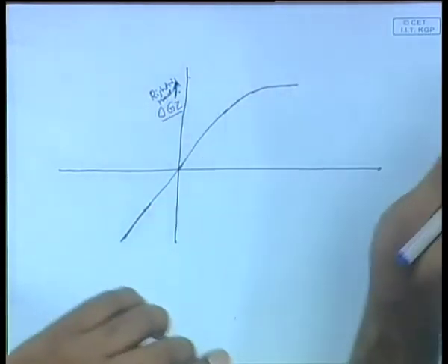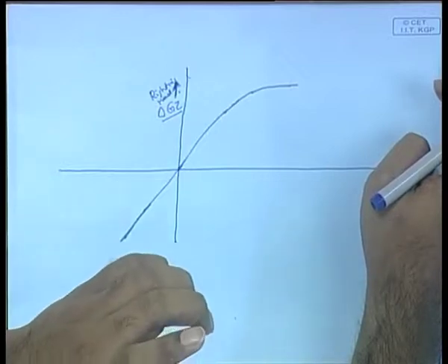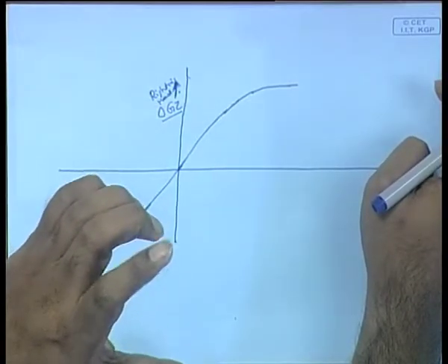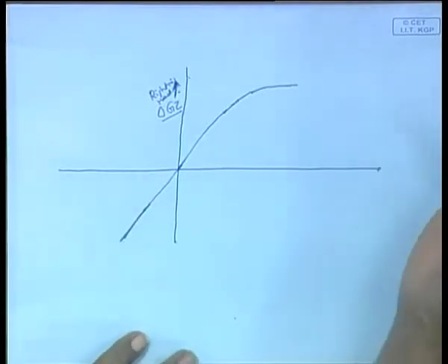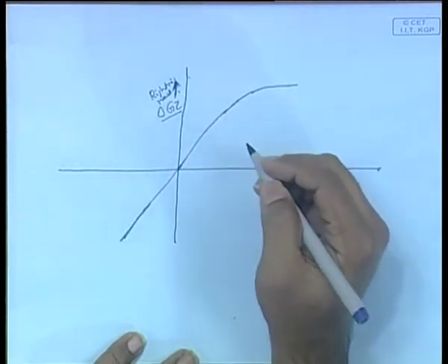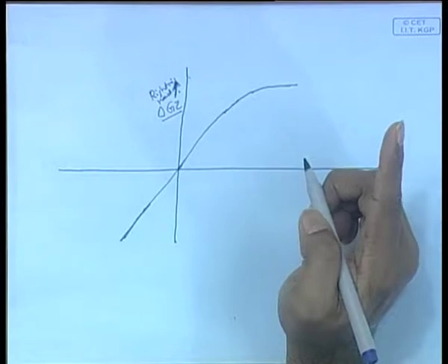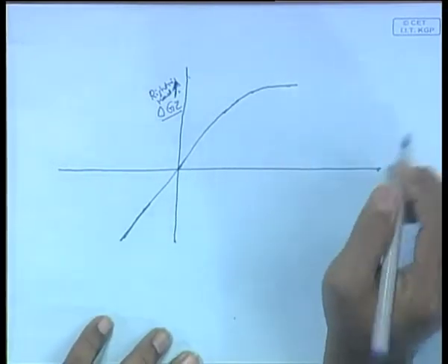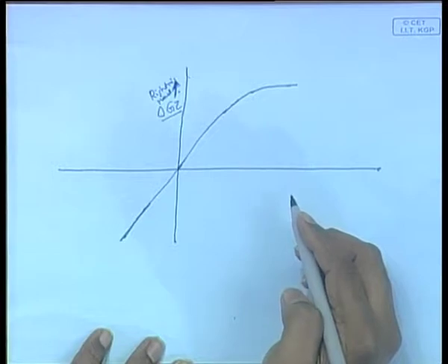Now, the important thing is that this is the moment phi curve, not the GZ phi curve. It is almost the same thing, it is delta into GZ versus phi curve. In this, instead of putting the heeling arm, we will obviously put the heeling moment. So, first of all, you put lambda 0, that is your heeling moment.